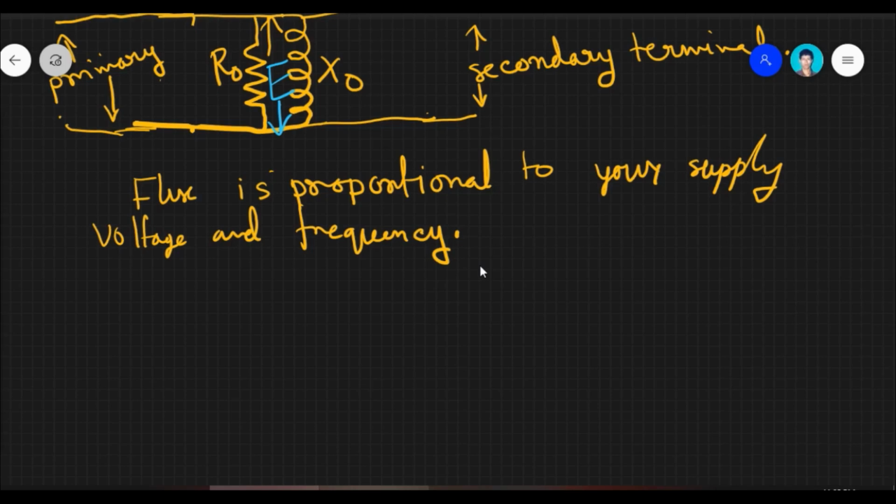So we will not be able to visualize this whole thing unless we connect a load with our secondary side. And more importantly, what we will observe is that this amount of leakage increases with the amount of load. If we put more load, then there will be more leakage flux lines that do not link both the windings.